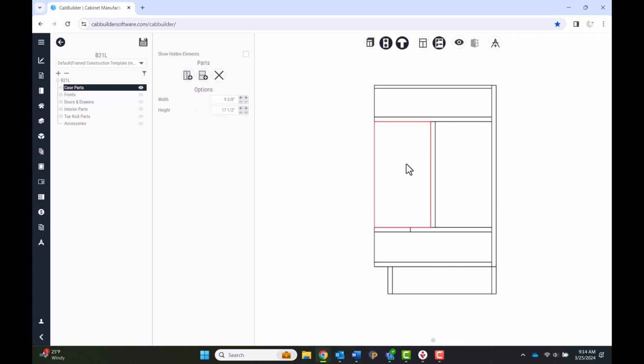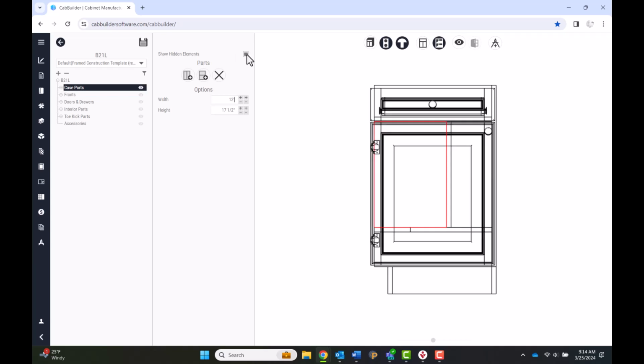The same applies to vertical interior parts, except the position value is a ratio of the space to its left relative to the horizontal space it occupies. And vertical elements are moved by changing the opening width, prioritizing changes to the right boundaries. The final control within the Inside section lies at the top of the Attributes panel, Show Hidden Elements, which will show or hide hidden front elements so that you may coordinate the placement of interior parts.